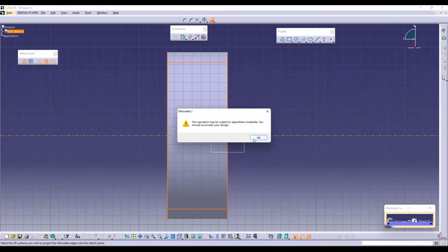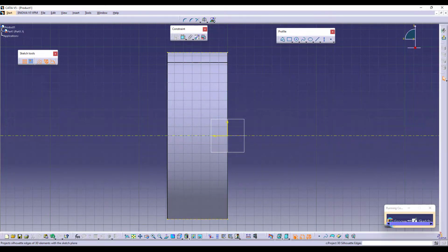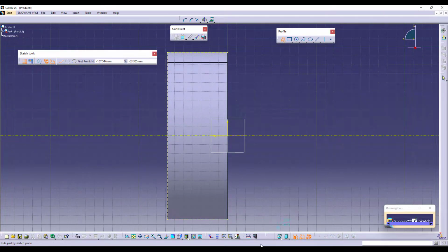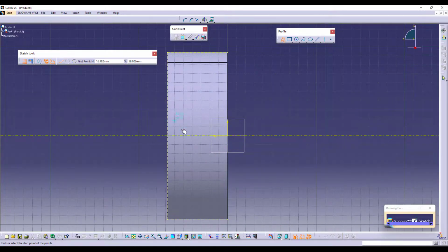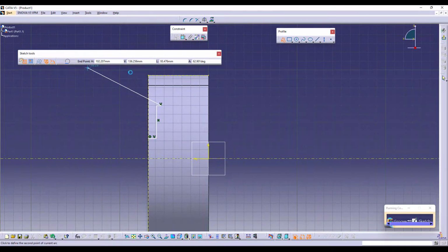Again, I'm selecting the ends of my cylinder as well as my edges to which I'm trying to make the cuts. Now, getting back to the actual sketch, see my sketch is actually this way, so I'd like to make that sketch first. It goes like this. And then I have an arc here, so I can change this to an arc.